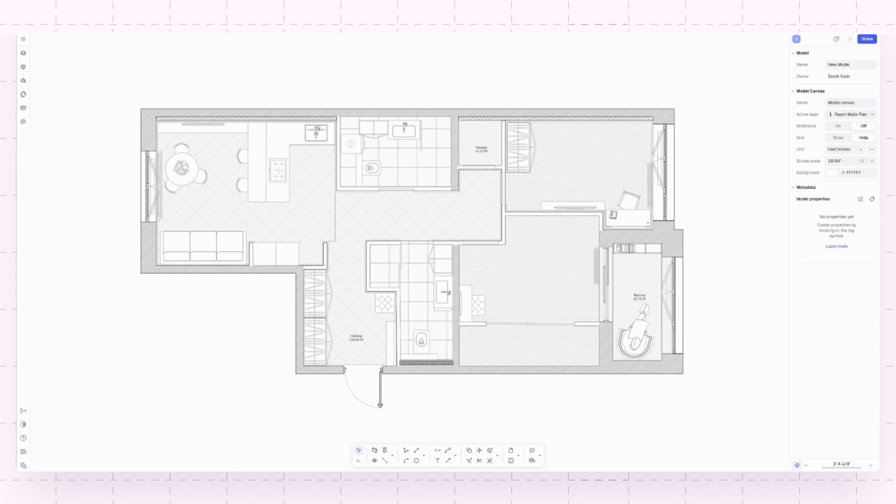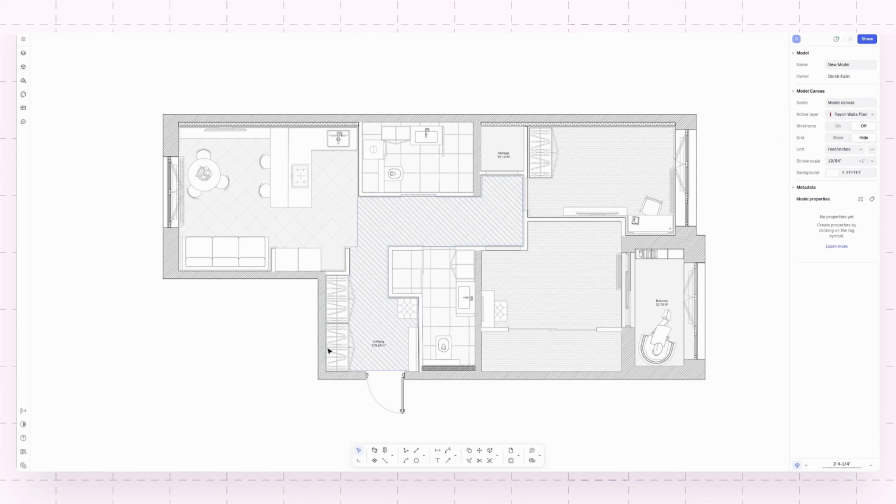For our last and final step for the drawing, we're going to be showing you how to add annotations. As you see, it already loaded some in for us when we made our zones, like this one and this one. But if we want to add some annotations, maybe saying what the furniture is, what material it's made out of, how long something is, you can just go down here once again, and you can either click on the text tool and just add in text yourself, or you can use the leader tool to label something, or the dimension tool to show how long you want a wall to be, or the arrow tool to point out an object and say, this object is what it is.